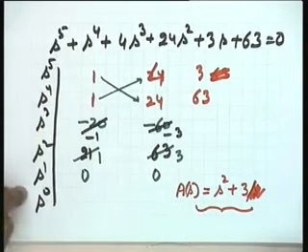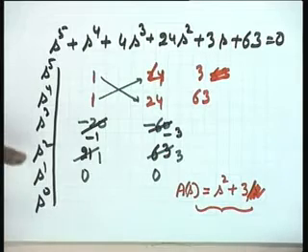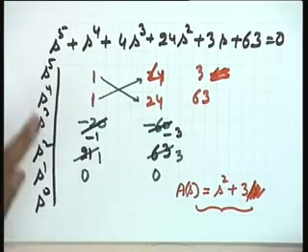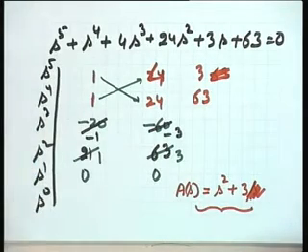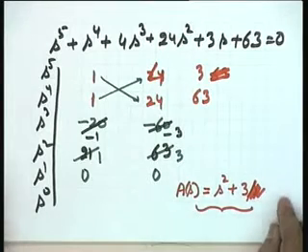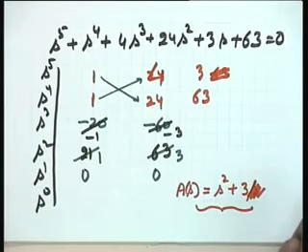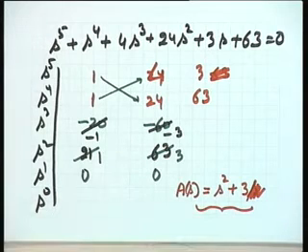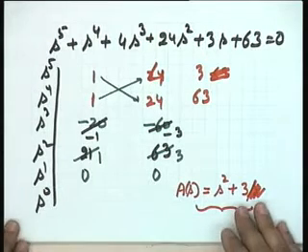It means in this particular case the roots are on the imaginary axis, and the system definitely is a marginally stable system if not an unstable system, because stability is yet to be determined. I explain the point again. Please see, when you come across an all 0 row, in that particular case you cannot proceed further with the array formulation.